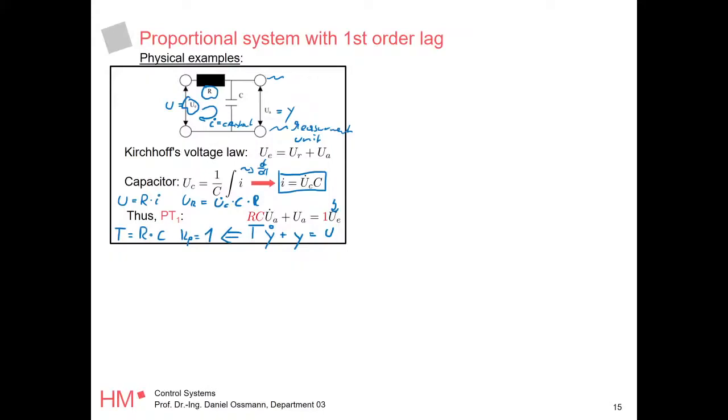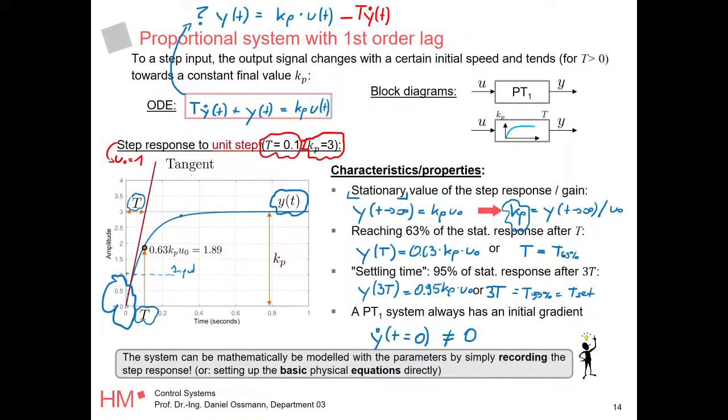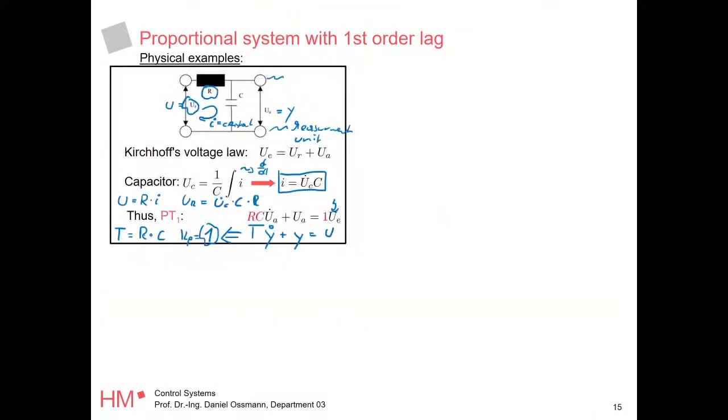Well, that means when we apply an input voltage, it's transferred exactly the same to the output voltage, because this gain here is 1, but only in steady state. There is a transfer behavior, like a PT1, like this here. It takes some time, and this time depends obviously on the resistance and on the capacity of the capacitor, and this totally makes sense, right?